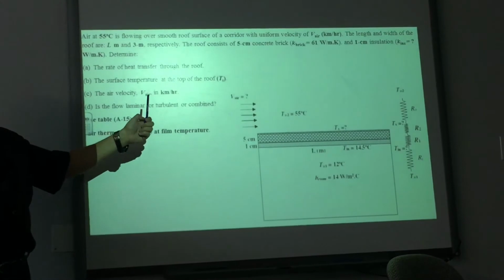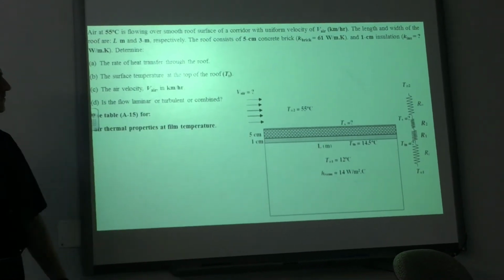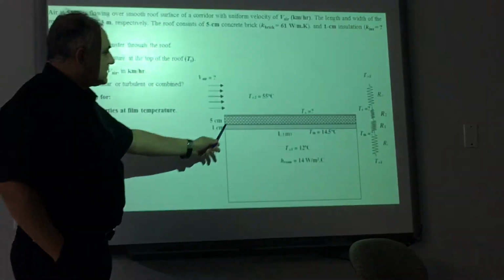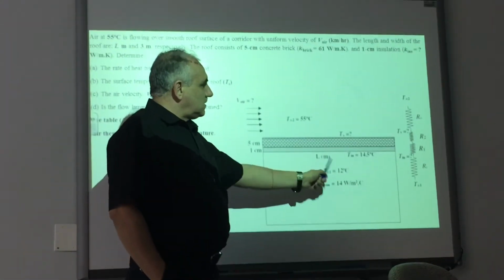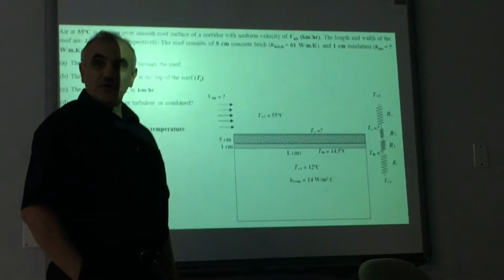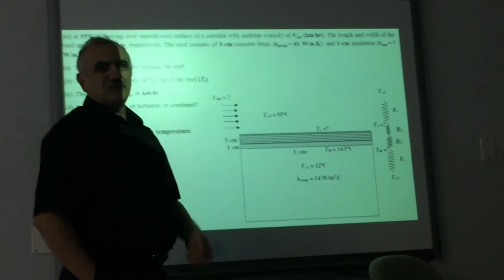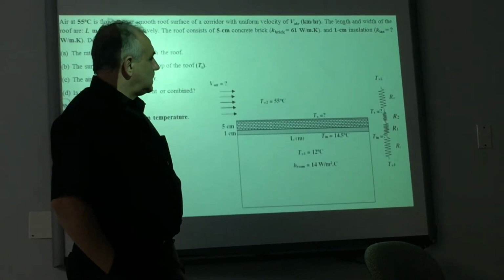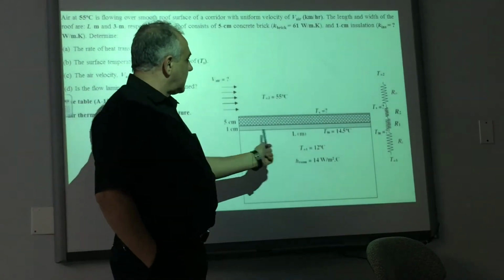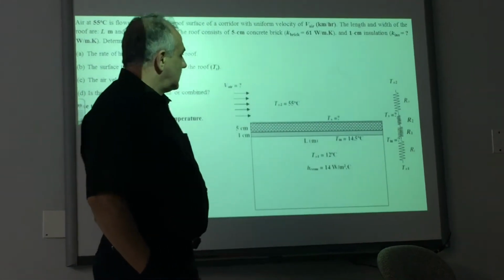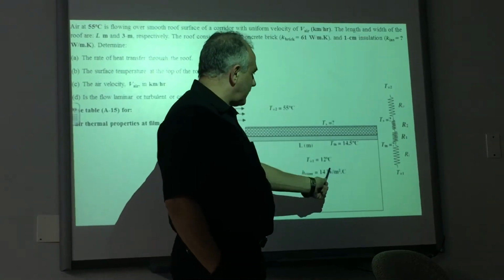Oh, and of course, if your case is laminar, you say laminar, because it's not a number. Okay? So here is the information you needed. Thickness known, temperatures, L, as I said, you will get it tomorrow morning, or today after midnight. What else do you need? L, as I said, and K. K for the brick is 0.61, and the temperatures, as you see, 14.5, 12.